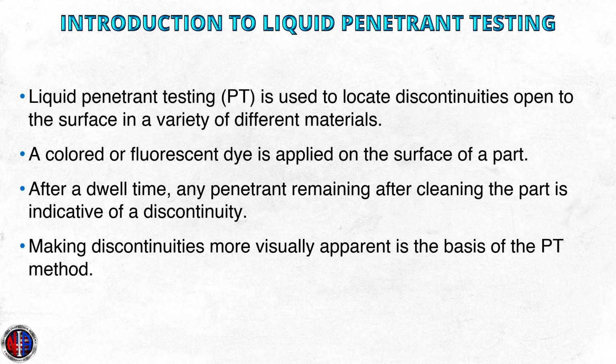PT not only makes the discontinuity indications appear larger, but it also provides a means to improve the contrast between the discontinuity and the part's surface with the use of color or fluorescence and a neutral background, typically white. Making discontinuities appear larger on a contrasting background greatly enhances their presence and visibility to overcome the limited visual acuity and contrast sensitivity of the human eye.